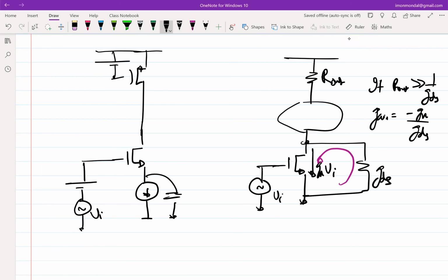So now let's look at it from the lens of resistances. If the incremental current has to flow into this box and not here, then can you comment on the input resistance of that box with respect to the GDS or RDS? Yeah, right. So the input impedance Rin has to be much lesser than 1 over GDS or RDS. Correct? Fine.